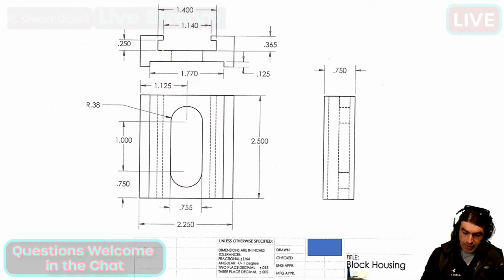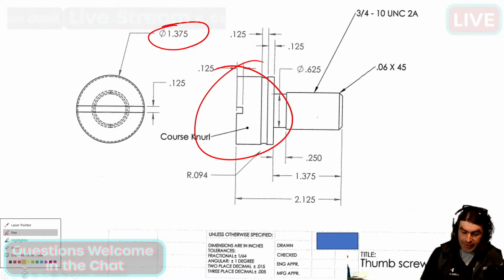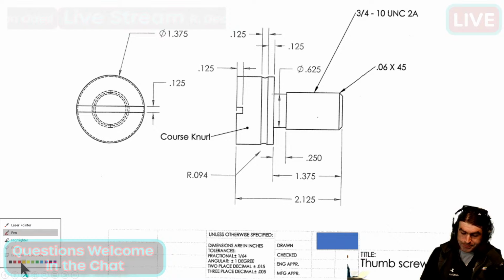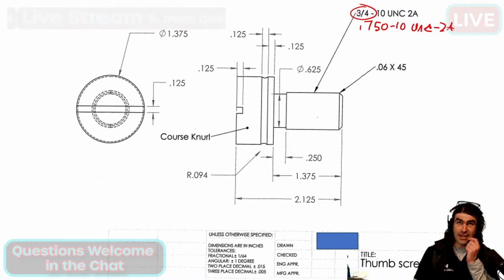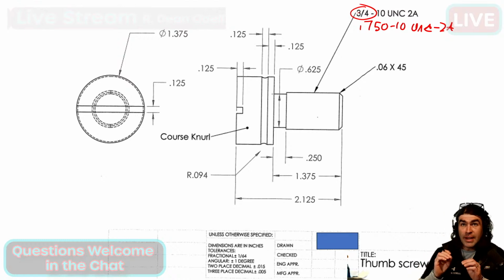The next thing, our bolt, the datum reference frames are kind of going to develop themselves. So the bolt sits down on here. I mean, we really don't have a lot of choices here. I guess it's not really against the rules, but I don't like fractional. I want to say it's against the rules in some obscure ASME standard. I like decimals there, except for pipe threads.